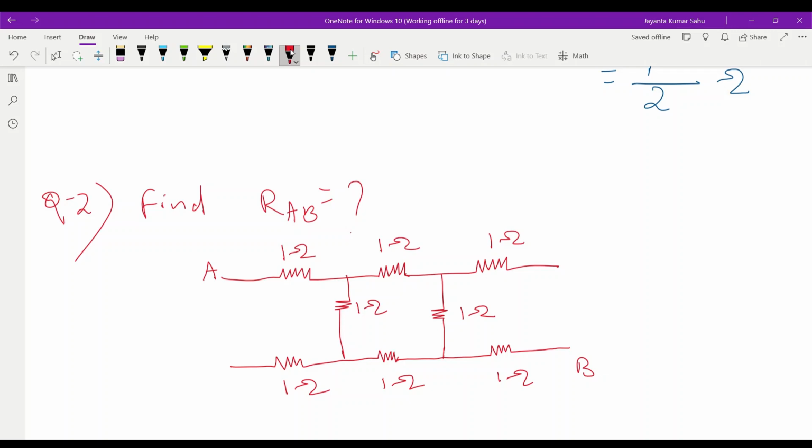A voltage source is connected between the terminals A and B. What will we do? If we find this type of question, there is confusion here. We apply the current method: if the same current is flowing, the resistances are connected in series. If the current is divided, the resistances are connected in parallel.